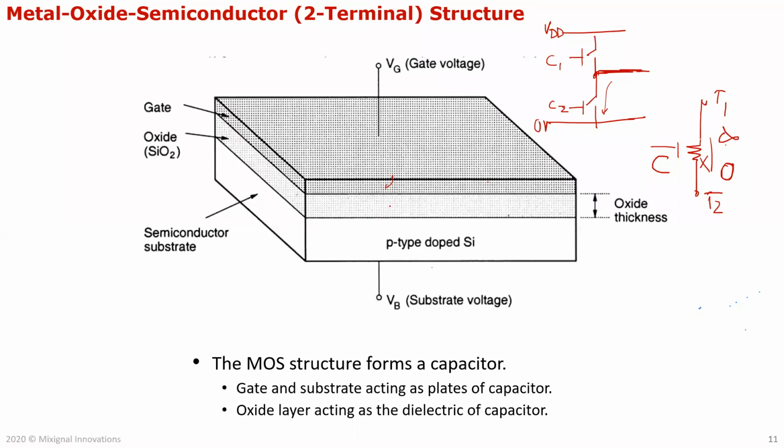All right, sorry. So you have an oxide layer here between a metal and some semiconductor. And this is essentially looking like a capacitor, but the difference is the other side is not a metal. So in a capacitor, you would have a metal, an oxide, or some other dielectric, for example, and you have another metal here.